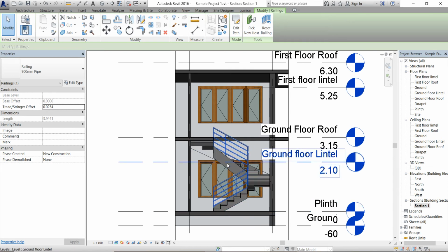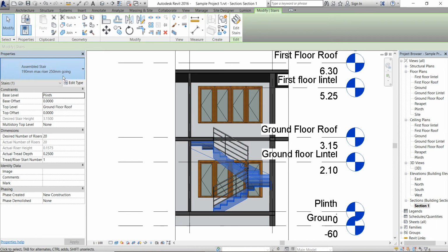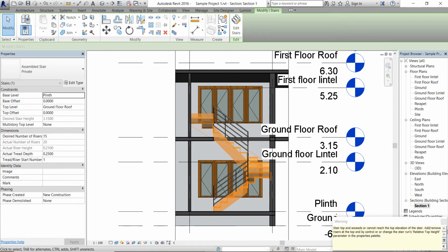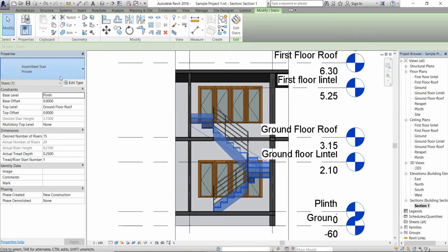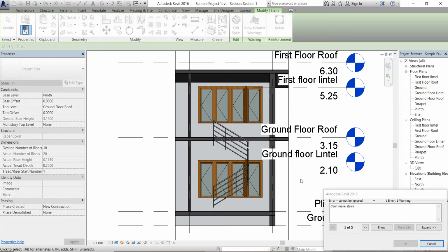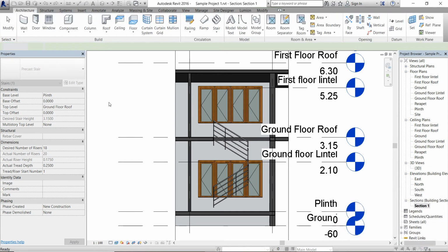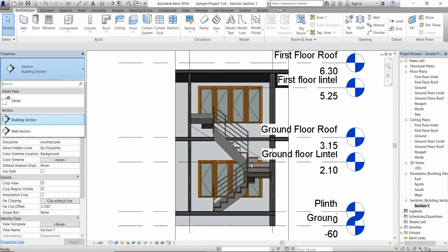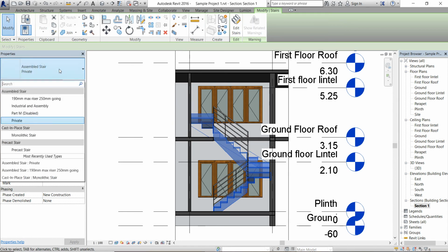The available stair types each have very different riser levels set by default. This is why when we change the type of stairs, the height of the stair also changes based on the preset riser level. Some railing types cannot be used with some stair types. In that case, there is a warning window and the railing gets deleted.